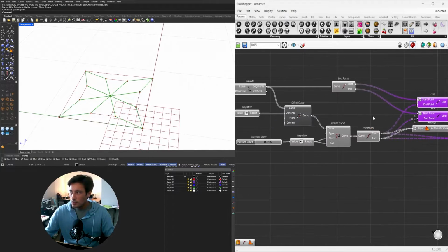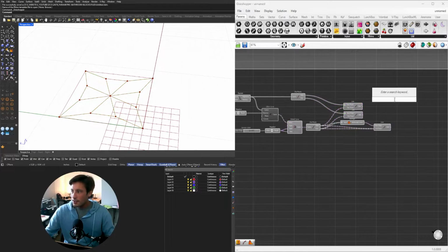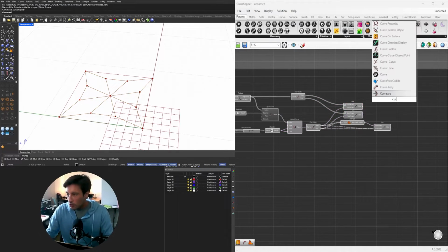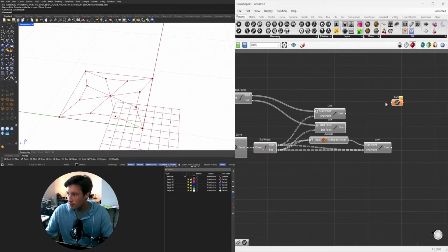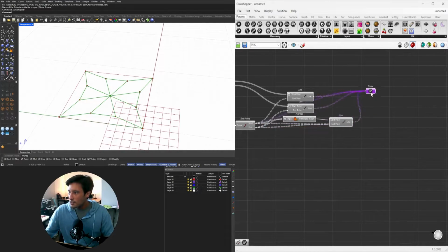And I'll show you, now that we have these curves, we're going to bring them together using a curve component so we can use those as a splitting mechanism for our surface. So I'm plugging all of these in, holding down Shift. They all go into this one. And sometimes when I route them all through one, it does create some confusion. So I'll go to Wire Display Hidden.